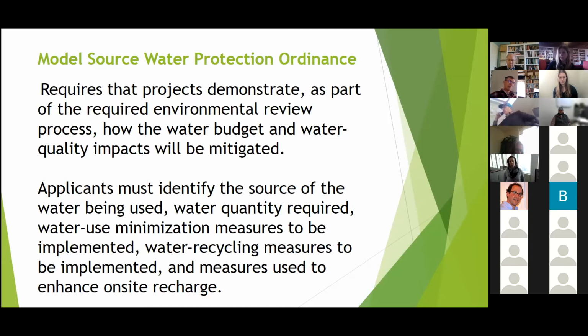And then if on-site wastewater disposal is planned back to the ground with septic systems, the model looks at some standard factors for nitrate loading, and once again determines whether the parcel is large enough that the aggregate recharge will bring the nitrate loading below thresholds such that we can consider it able to, in a sense, digest its own wastewater without offsite impacts. And so baking that into the model ordinance provides information to the planning board to determine whether a project requires higher scrutiny or can just be moved ahead because it in a sense is really sustainable both on the consumptive side and on the wastewater processing side to proceed without further inquiry.